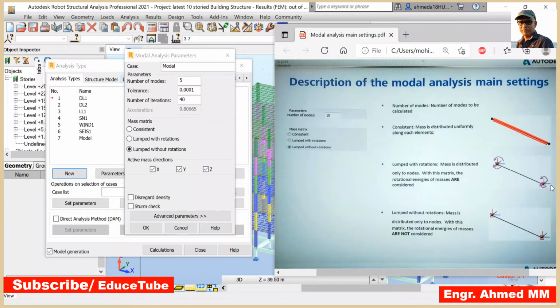So mass is at both nodes. As well, it says with this matrix, the rotational energies of the masses are considered. This is rotational energy of masses. That is why they put the rotational sign here. Directions are there for rotations. So both are the same except one item, that this is without rotation. That's why there is no rotation arrow here. So we got the understanding of this mass matrix.